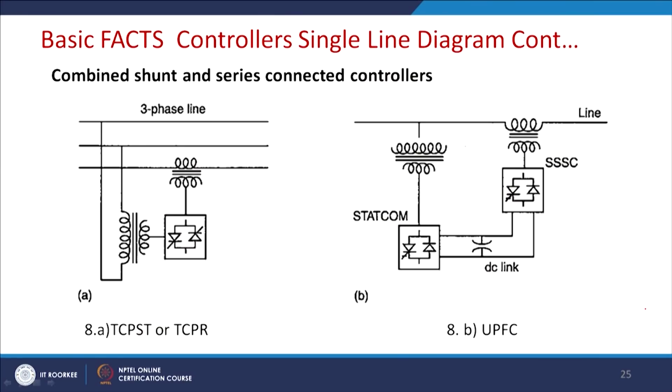Now let us come to the combinations of FACTS devices. This is a combined shunt and series compensated controller, and this is called TCPST. This is essentially a phase angle regulator, and this is a UPQC or UPFC. This is a series shunt combination. This part acts as a STATCOM and this part acts as an SSSC for the series compensation. So, altogether the advantages of both series and shunt are captured here.